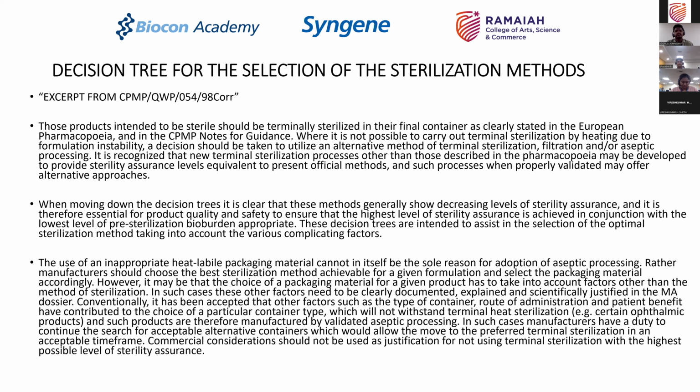Again, as I said, it is not possible to go there in every situation. If your product itself cannot withstand heat, then the question of terminal sterilization does not arise. So a lot of biologics products which you are manufacturing today through monoclonal antibody formulations, and a lot of other products in the industry, some of the complex injectables for example, terminal sterilization is not an option because the formulation itself cannot withstand the heat. And in such a situation, your only choice is aseptic processing.